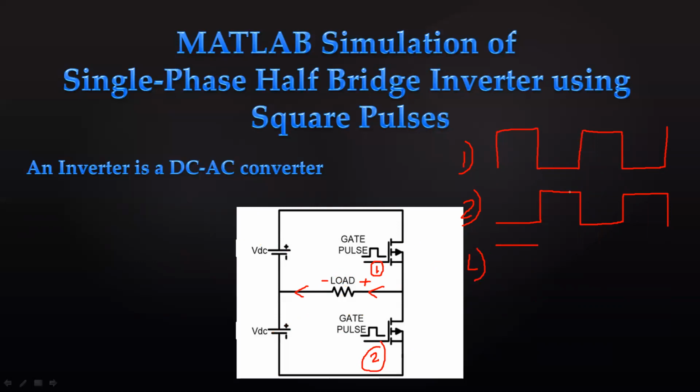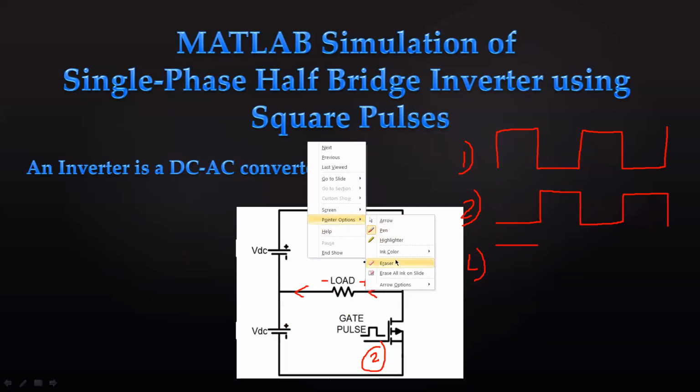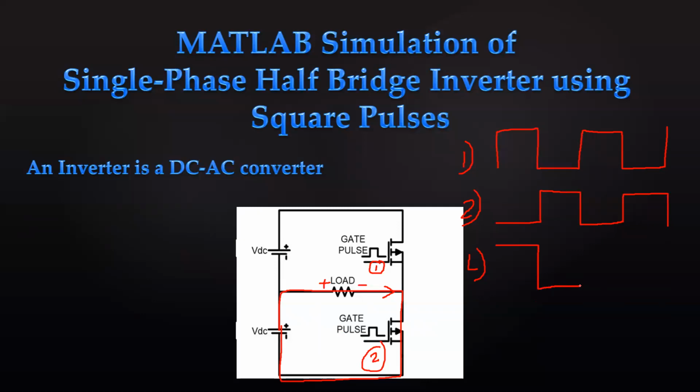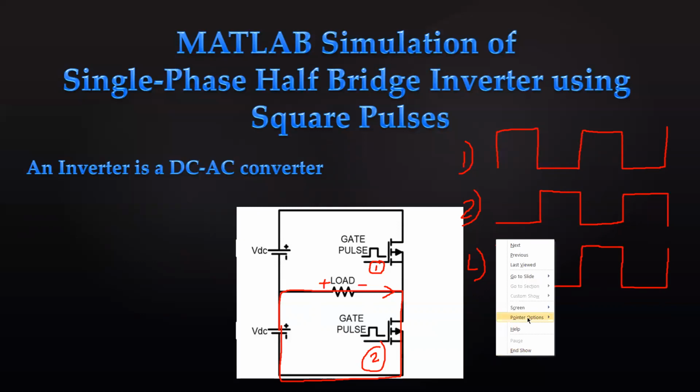Now, in the second 50%, what we will get, this VDC will work. So current will flow from here. This will be positive because the gate pulse in the second half is positive for the second gate. So it will be plus here and minus here, and current will travel from this to this, right? That means current is negative. So it will go negative, it will come here, it will continue, right? So for a DC input, we are getting AC output.